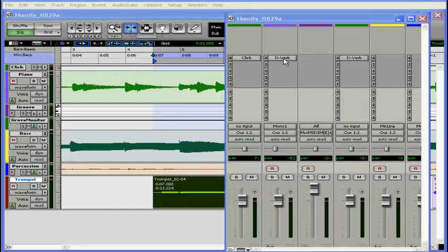Okay, let's talk a little bit about the kinds of effects. There's many kinds of signal processing that are commonly used in audio. They can generally be grouped into two categories, dynamic-based effects and time-based effects. EQ, or equalization, compression, expanders, gates, and limiters. These are effects that change the dynamics or frequency and volume of your audio signal. Normally, you'd use these on inserts rather than sends because you don't typically blend a processed and unprocessed signal together. You're going to need 100% of the audio processed as it plays.